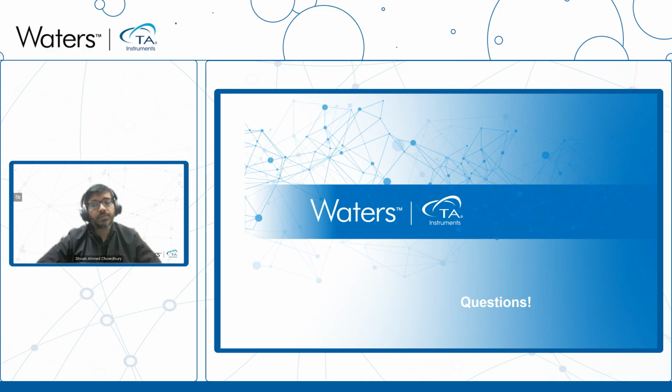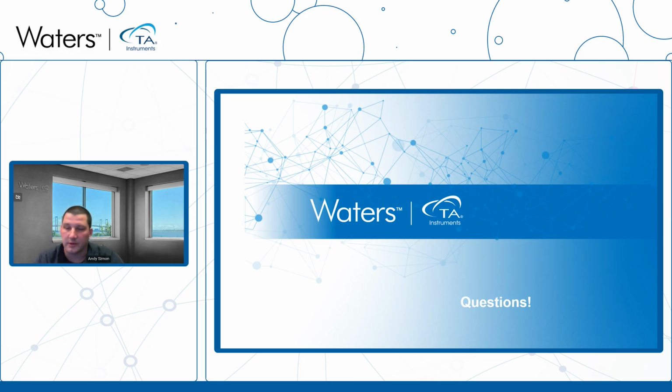Thank you. So the next one here: we all know that plastic parts should generally be designed with the knit lines in lower stressed regions of the part. You don't want to put it where there is the highest stress. So is the fatigue performance of that knit line really that critical?